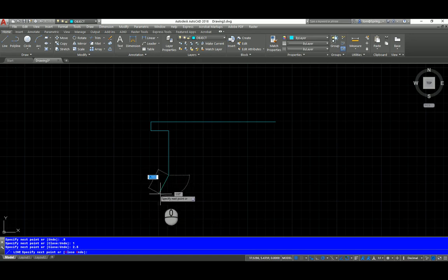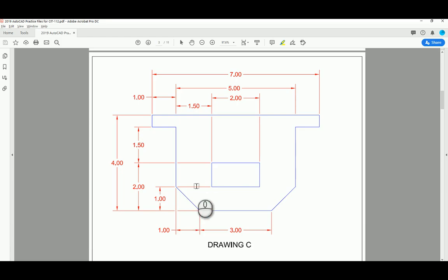Now this is where you could use the Pythagorean theorem, but as I'm fond of saying with AutoCAD, that's too much like doing work. What we want to do right now is find a point that actually is going to give us the x and y that we see here. So the x and y that we see here is over to the right 1 unit, and it's going over to the right 1 and down 1.